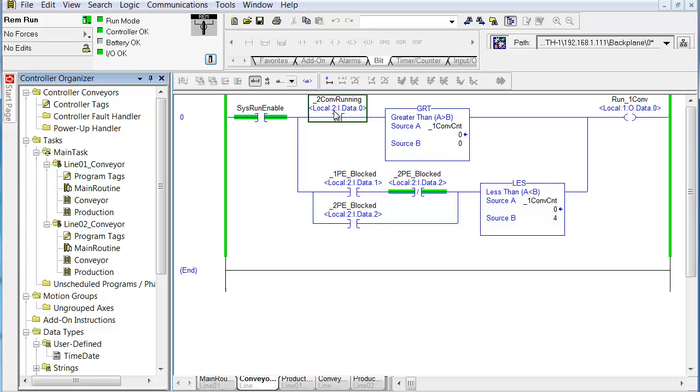If you wanted to execute this logic, first of all, you have to either have 5000 Emulate or you have to have a Logix processor: ControlLogix, CompactLogix, SoftLogix, FlexLogix. You have to have the Logix engine in hardware to execute the code, whether it's Emulate, which is really SoftLogix 5800. They're basically the same thing. And so you have to have the Logix engine to execute the code. So if you don't have that, then it's irrelevant.